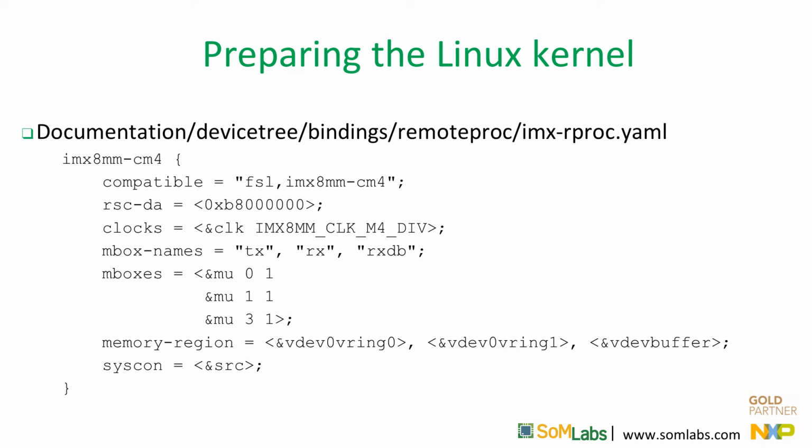In the mentioned patch file, 3 new sections were added. The I.MX8M CM4, rpmsg, and the memory blocks required by these peripherals. In the I.MX8M CM4 section, a compatible device is defined, which is of course a Cortex-M4 within the I.MX8M, and the mailbox is used by it.